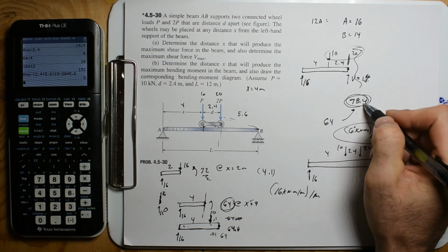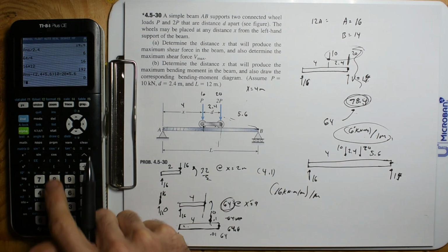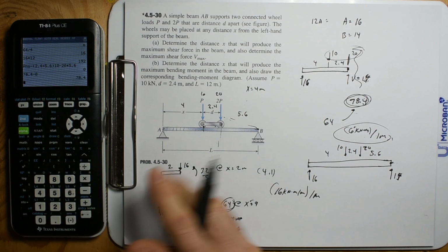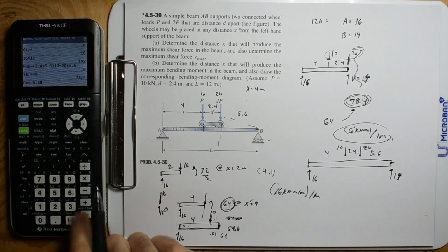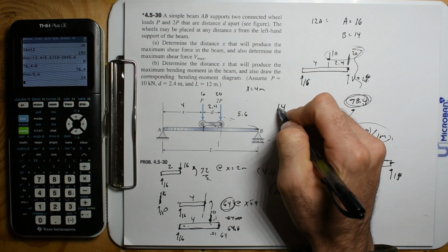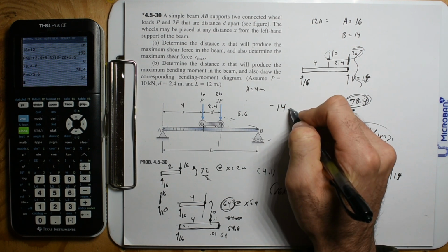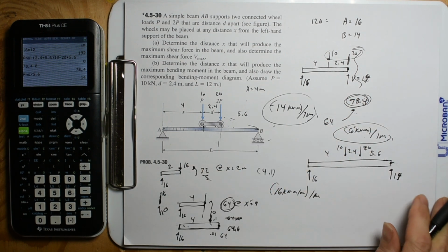And it's going to be linear. So we're going to go from 78.4 back down to 0. So 78.4 minus 0, that's the change over 5.6, so divided by 5.6. That's going to be negative. So we're going to change by 14 kilonewton meters per 1 meter. You know what I mean? So that's going to be the slope downward.